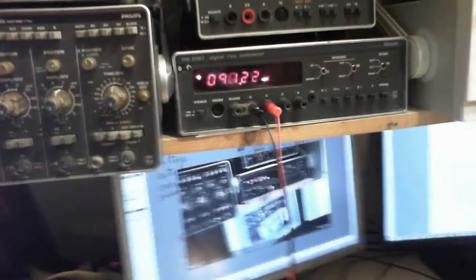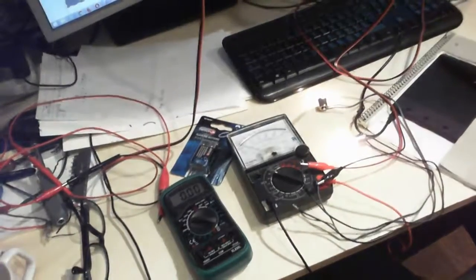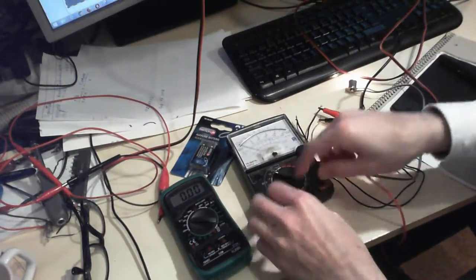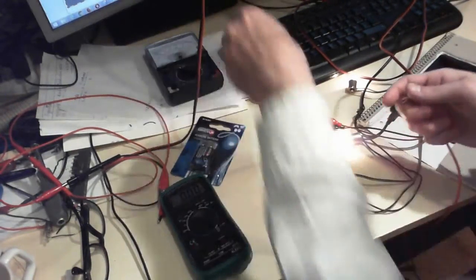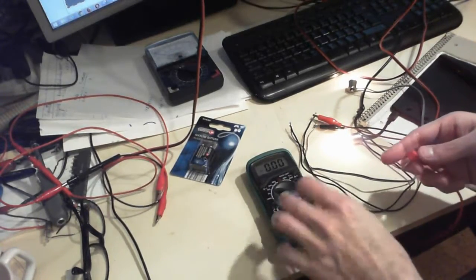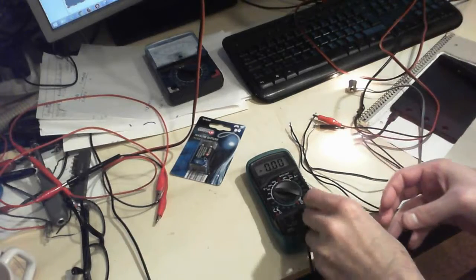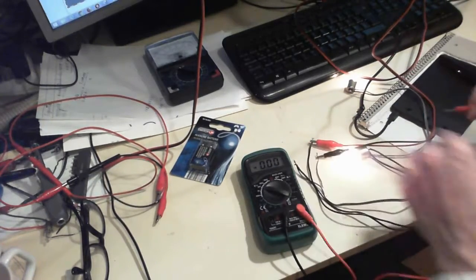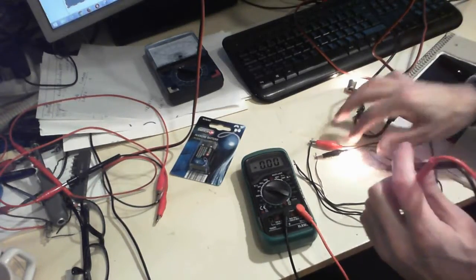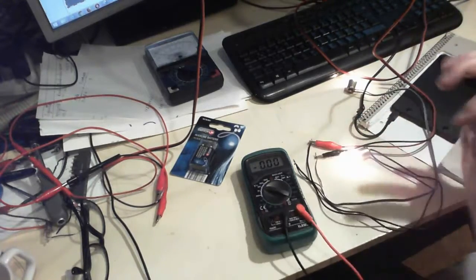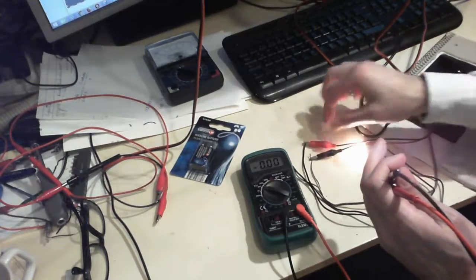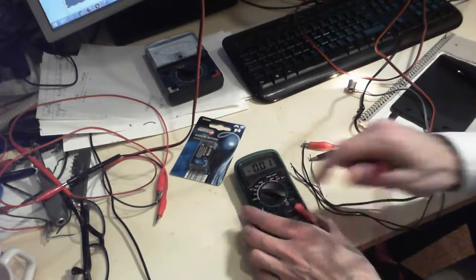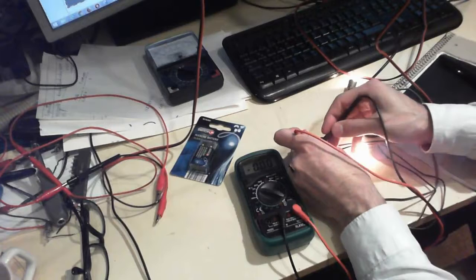Let me see. Okay, so I have another multimeter. It's not easy to read this right now for you, but you can read this. So this is the exact same thing that we had up here, just a very cheap version, very cheap. So you can see that the lamps, both of them are lit in series, and this wire is coming from my power supply. This is positive, this is negative. So I can set this to volt DC 20 volts and probe this power supply.